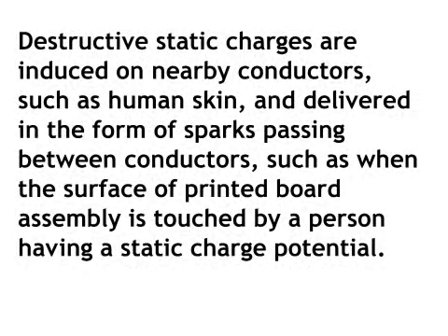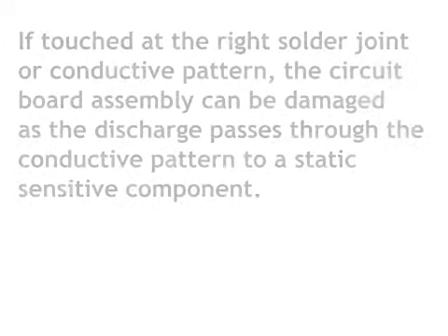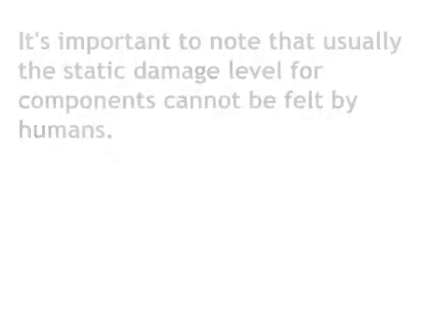Destructive static charges are induced on nearby conductors, such as human skin, and delivered in the form of sparks passing between conductors, such as when the surface of a printed board assembly is touched by a person having a static charge potential. If touched at the right solder joint or conductive pattern, the circuit board assembly can be damaged as the discharge passes through the conductive pattern to a static-sensitive component. It's important to note that usually the static damage level for components cannot be felt by humans.